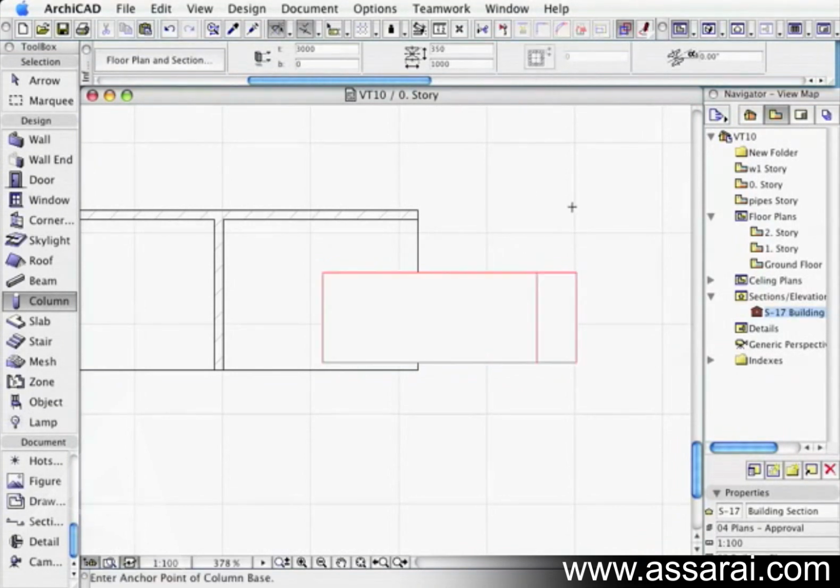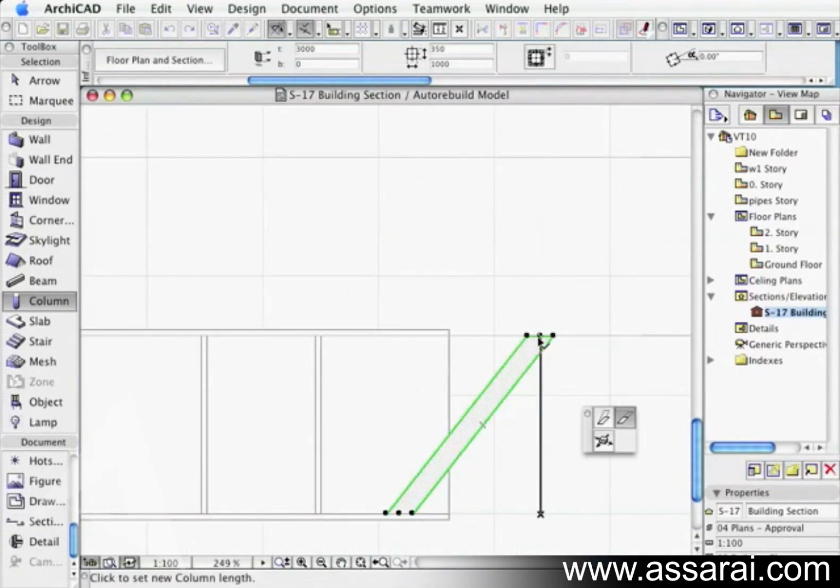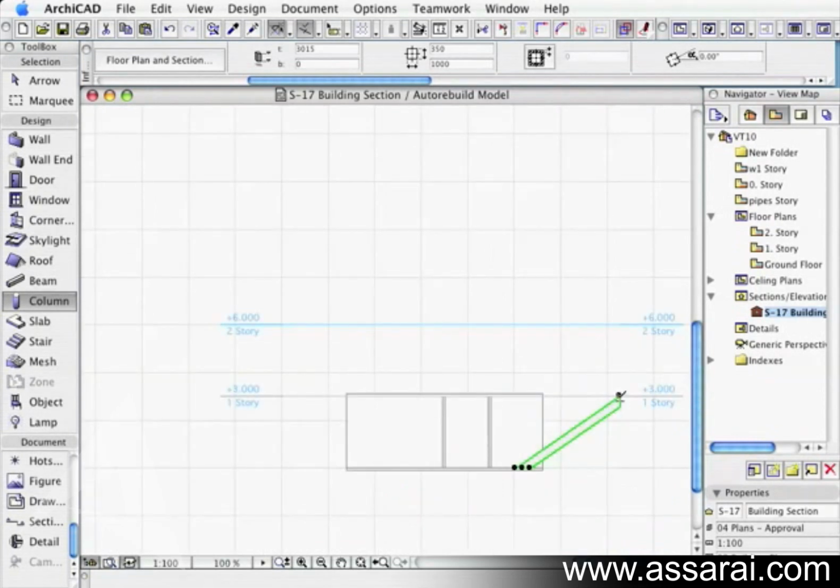But if I go to the elevation window, we can see we have the same functions in the elevation window. So if I select it there, the first icon lets me change the height of that in a vertical plane, and the second icon lets me extend that along the plane, or along the inclination path of the beam. Over there my section line runs out, so I might just drag that back a little and move that straight up.